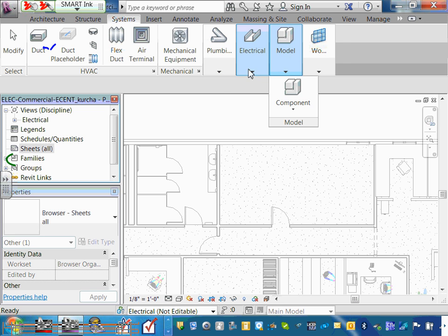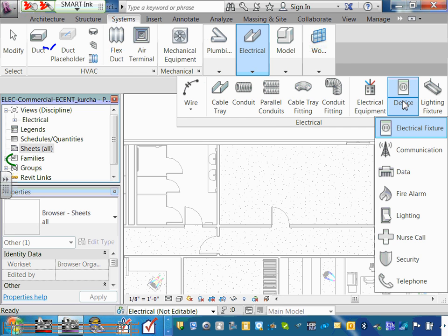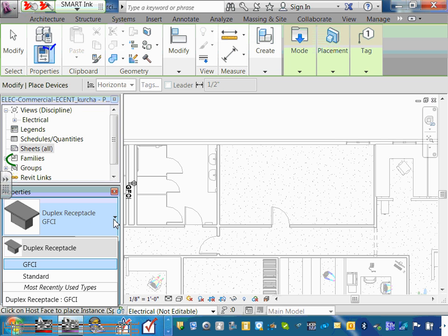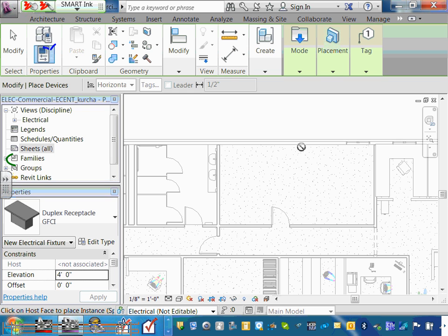Okay, gentlemen, one more time. I'm going to go system, electrical, devices. I'm going to click on device here, duplex. Did you guys grab a GFCI? And go drop a GFCI in that room. Did you guys drop a GFCI? Just click next to the wall. Can you see, Jay, you and Tony, when you're hovering here, it says you can't put the receptacle here. You have to put it in a wall. It's attached to a wall. Can you see how it adjusts itself to the wall?